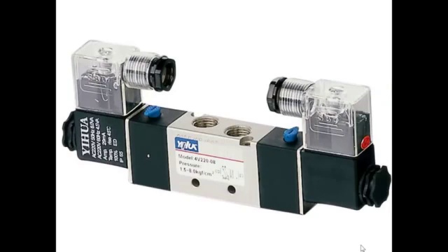This is a pneumatic valve. This is a solenoid valve, and on each end of it you see electrical connectors. So inside the black plastic, we'll call them boxes that have the little knobs on the end, are coils of conductor, and then in between the two black boxes, going through the entire body of that valve body, is a spool.